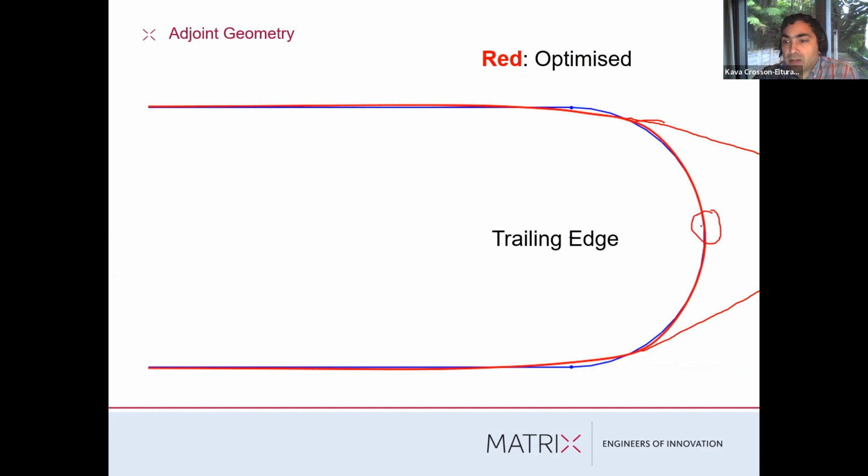It hasn't really changed the geometry that's sitting in that dead zone of the wake at all. It's focused on sort of the area where separation is occurring. So I thought that was pretty interesting. I guess you could see that as progressively working towards delaying separation, and it might eventually work its way back to develop some more fairing-like geometry, but in this case, it hasn't done that.